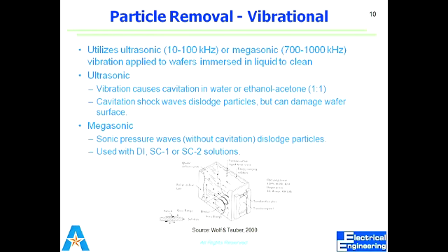Due to those waves, bubbles form and immediately collapse. When a bubble collapses, you get a liquid-free space or cavity. So when you have the vibrations, you form and collapse the bubbles, which are called cavitation bubbles. That cavitation is the process that makes the surface of the wafer clean.